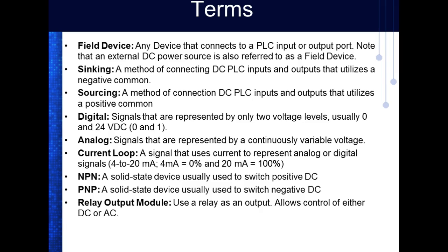The problem we have with using a voltage is that electromagnetic interference gets voltage into conductors. But this electromagnetic interference can't generate a current, because there's just not enough energy or coupling there, right? You understand? So anytime we start dealing with what we call high resistance circuits, then we're very, very concerned with what we call EMI. You know what EMI is? Electromagnetic interference.